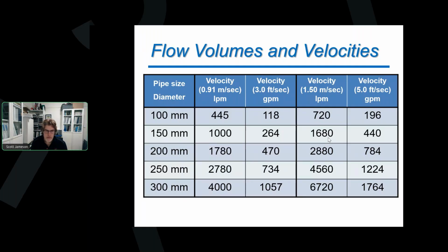Right, you've got 50, 60 psi static, and it does not drop greatly when you open up the fire hydrant, you're going to achieve these flows quite easily. But again, make sure you have some sort of pitot to measure that, right? So you can confirm that yes, this is what my UDF is doing, I'm achieving the goals that I'm trying for.